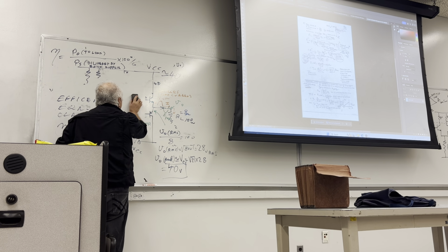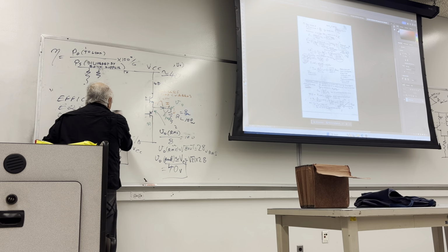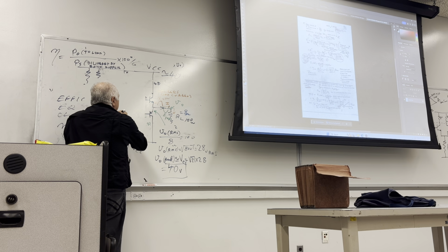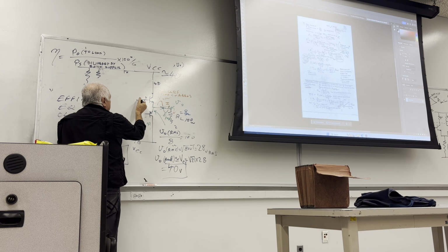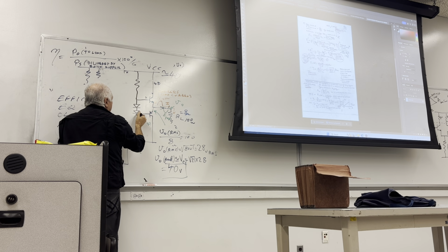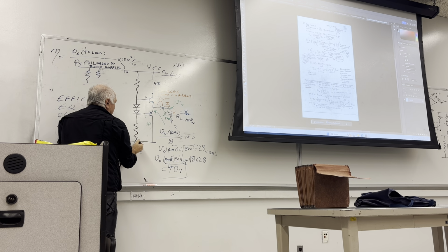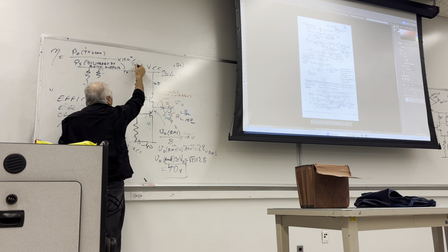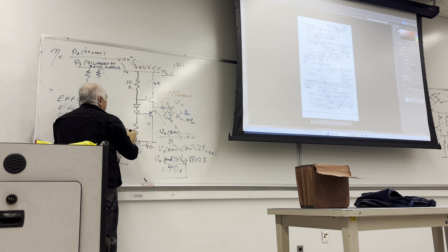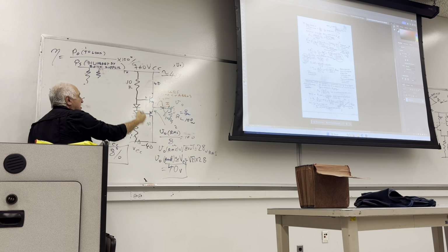so they put actually this assembly here. The cheapest way. A diode here, a diode here, a resistor here, identical resistor here, minus VCC, plus VCC, and say 10K, 10K, exactly symmetrical.